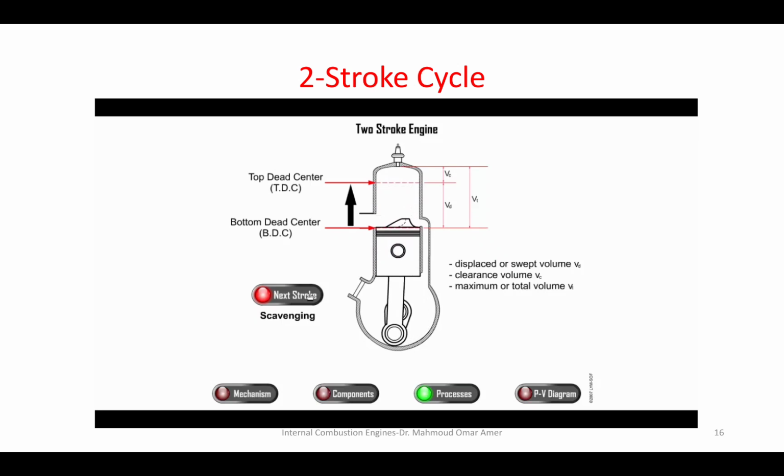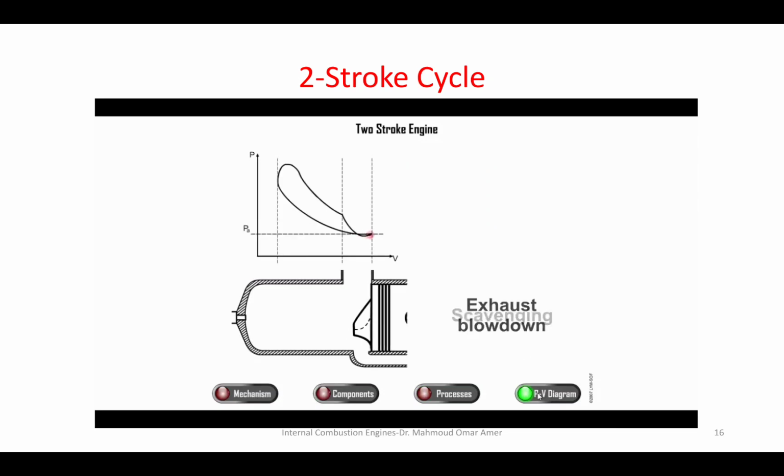Okay? But how about the quality of the charge? The quality of the charge is very low. Why? Because you do not wait for all the exhaust to exit. During the exhaust exiting, you input the fresh charge.